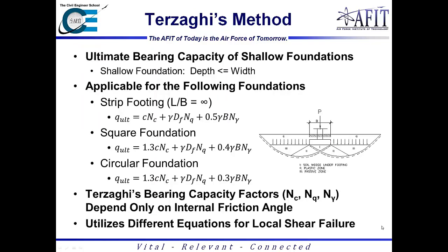The first method we're going to talk about to calculate the ultimate bearing capacity for shallow foundations is the Terzaghi method. So for shallow foundations, we're generally looking at the depth being less than or equal to the width. And this is pretty much the primary assumption that you need for the Terzaghi method. If this isn't true, you have to go into basically the Meyerhof method, and I'll get into that in just a few minutes. But the Terzaghi method varies depending on which foundation you're actually looking at.